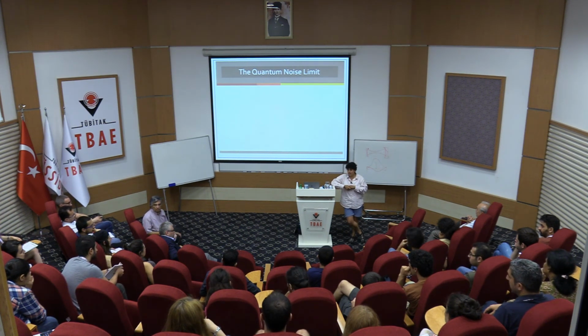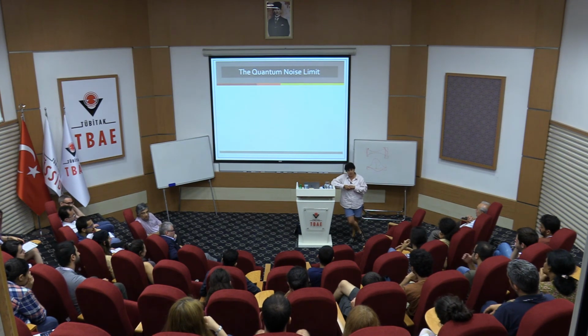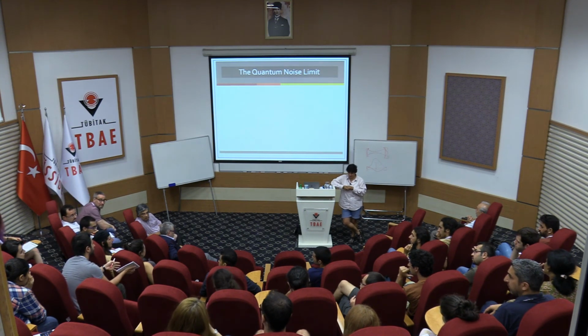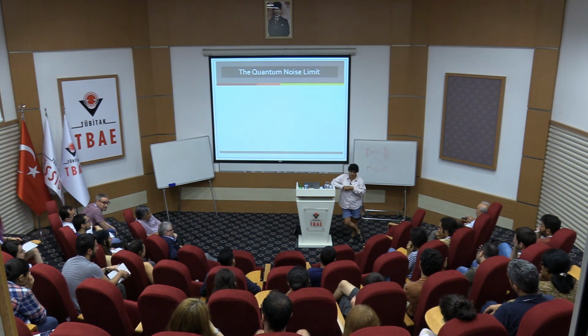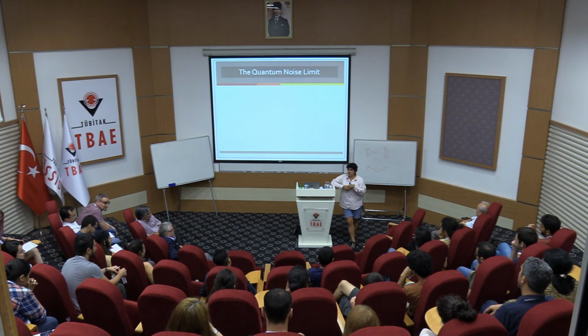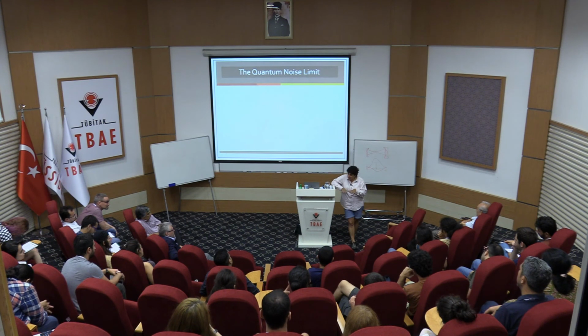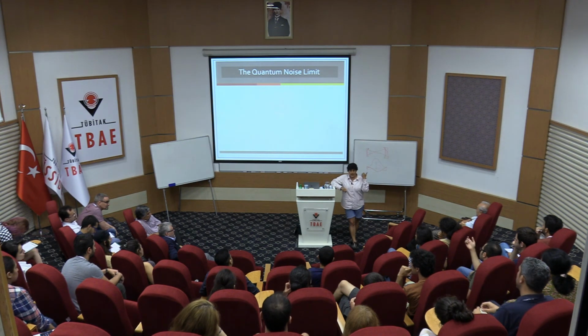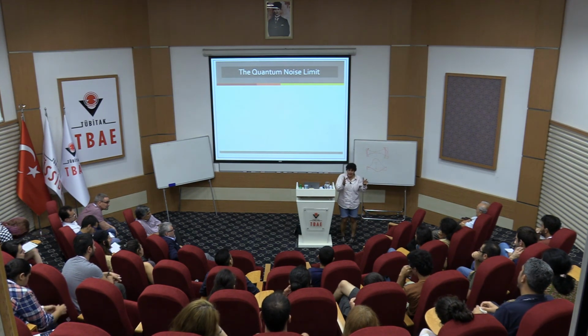But remember our motto, if you can measure it, you can cancel it. So we put all of our effort into measuring. I was wondering, what do you use for this kind of active control system? What kind of instruments do you use? Yeah, so let me preface the answer by saying that in LIGO we have over 2,000 control loops. In the case of the seismic vibration isolation system, we might use a seismometer, or any other kind of vibration or motion sensor, to measure the motion of the payload and then feed back.